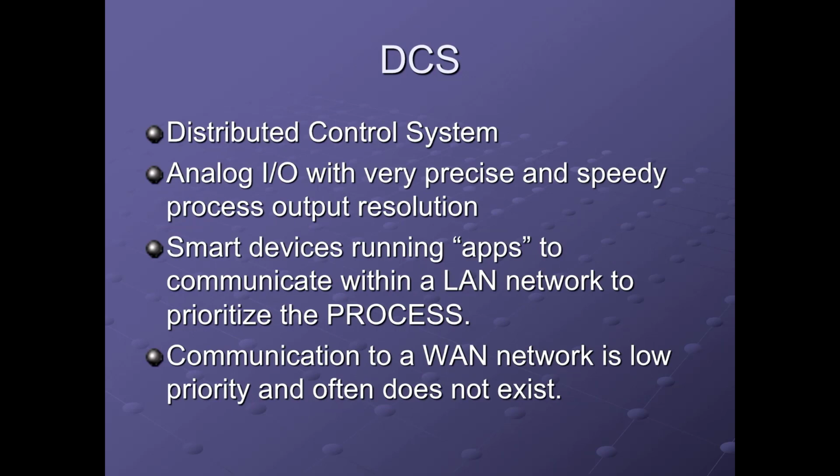So DCS is distributed control systems. Again, just about exclusively analog I/O, and it's really all about the process and a speedy resolution of an output based on variable inputs. So it's all about the process and the speed of resolving that process.